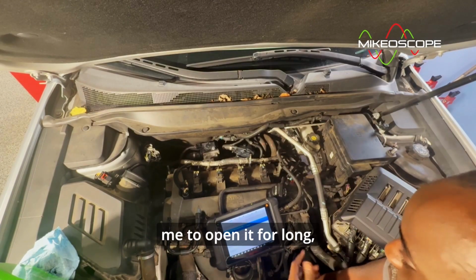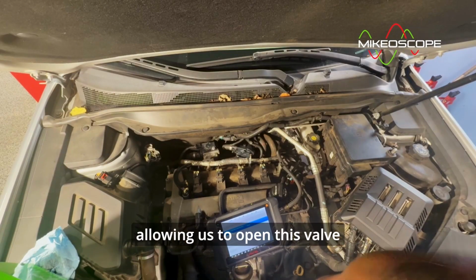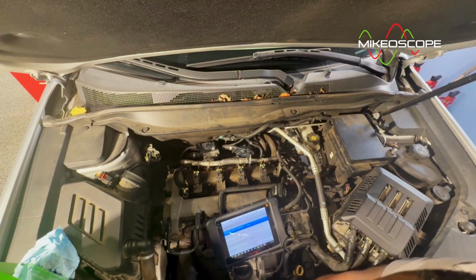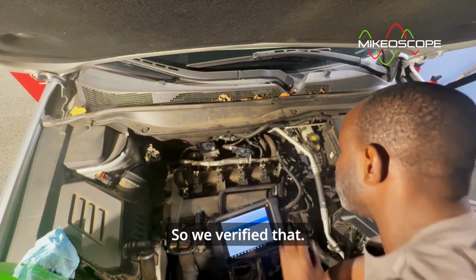The ECM doesn't allow me to open it for long, just a very short time, which is why we didn't get to see it at the exhaust, because it wasn't allowing us to open this valve for long enough to accumulate enough smoke to see it at the tailpipe. So you can see this valve here works, so we verified that.